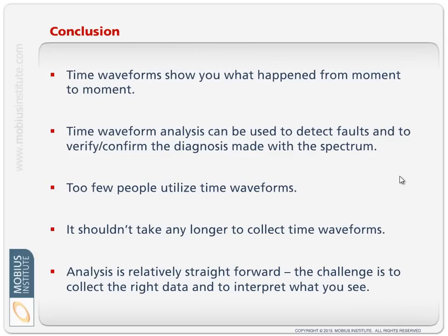Now, time waveforms show us what happened from moment to moment. It's like taking that movie and analyzing every frame of that movie. Okay, as the gears mesh together, is it going well? As the balls roll around, is it going well? It gives us that detail. Not enough people use this tool.